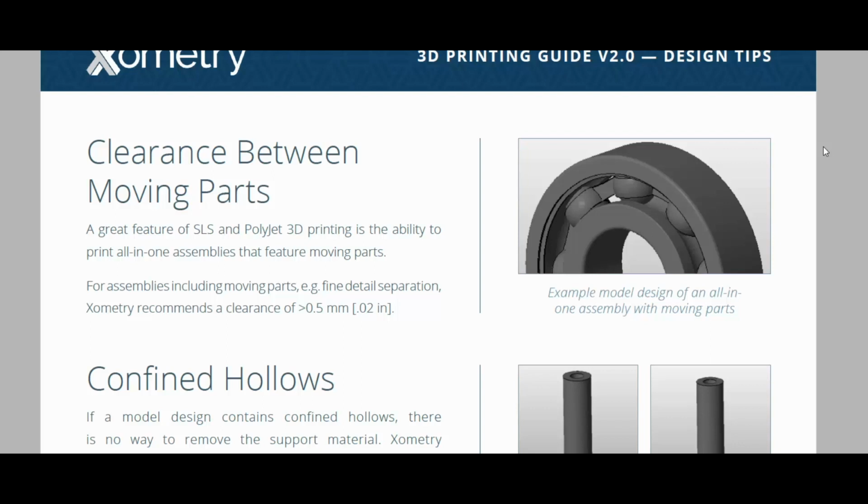When parts are moving, so if you're using a powder bed fusion technique like SLS or HP Multi Jet Fusion, you may want to consider adding at least 0.5 millimeter gap clearance in those parts. That makes sure that the parts don't fuse together while sintering. If your parts are more dense together, you may also want to add a little bit extra to that clearance, maybe 10% or 20% more if you have the chance. That's going to prevent any over fusion from those parts' densities actually heating up and creating more of a fusion than typical.